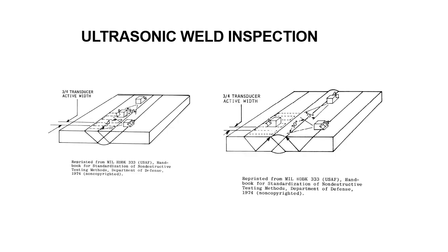Here's one where you can use a transducer on a weld where the weld has been ground flush. You can see that on the left-hand side. And then you've got the same thing that we were talking about in the previous three slides on the right-hand side, where you've got the transducer and you're scanning the weld, and it's giving you a pattern.